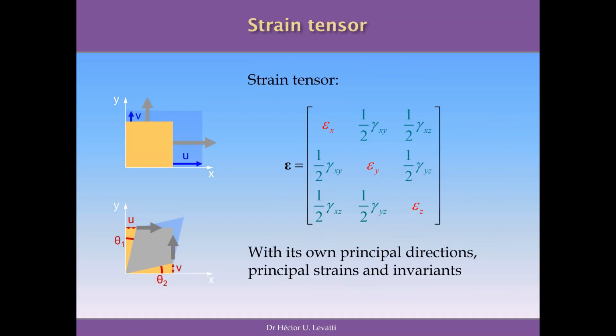In the same way you have stress tensors, you have strain tensors as well. And this is the definition of the strain tensors in geotechnical engineering or in structural analysis, it is the same. So in the diagonal you have the axial strains, and the rest of the components are the distortions in your problem, at any point, at any element, square element or cubes in 3D.